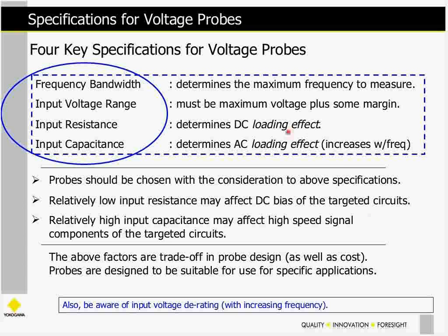When you look at the specs for voltage probes, this gets overlooked a lot. Go back to the specs section of the manual and look for derating. This is true for current probes too. So that means with increasing frequency, my probe is actually less capable, and I need to consider, will that still make my measurement that I want to perform successfully for me?